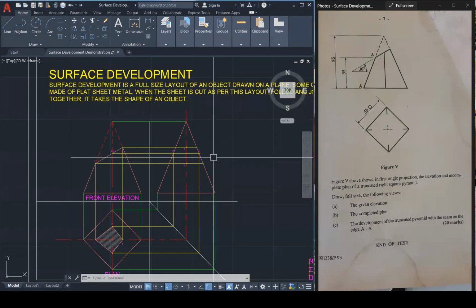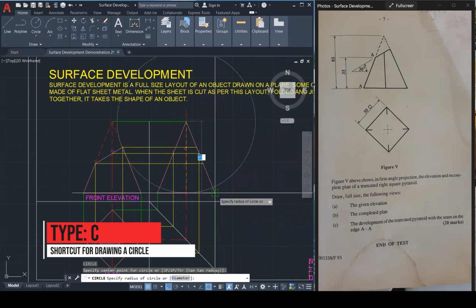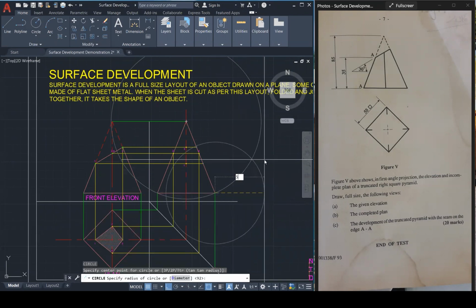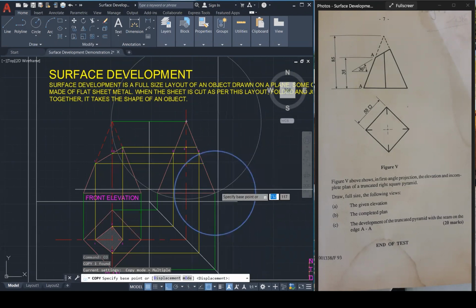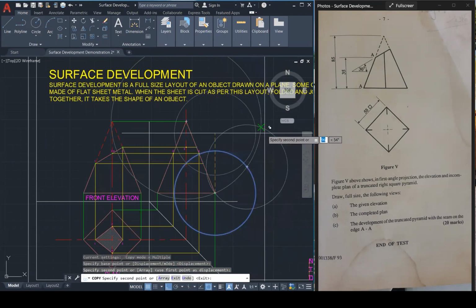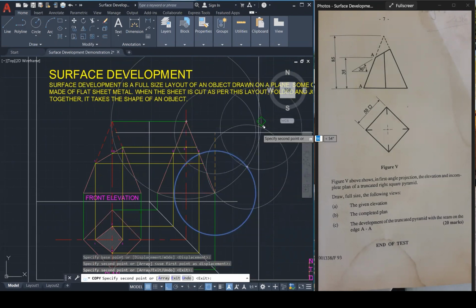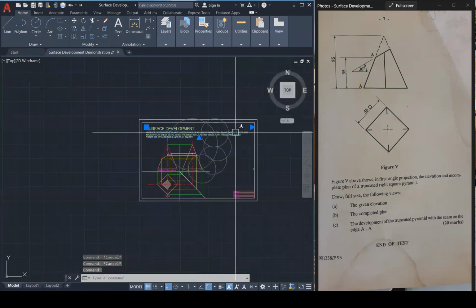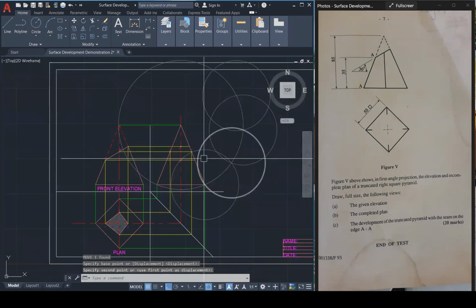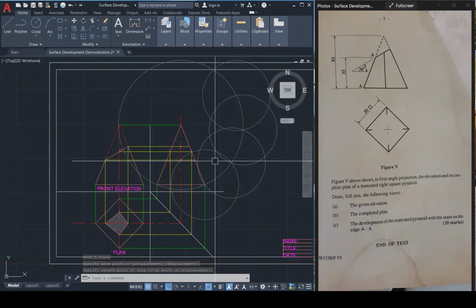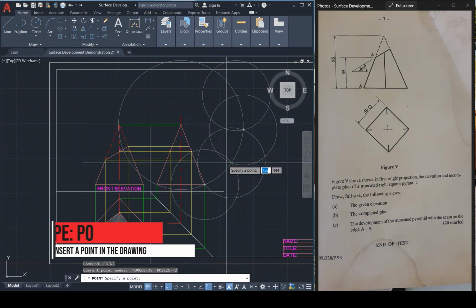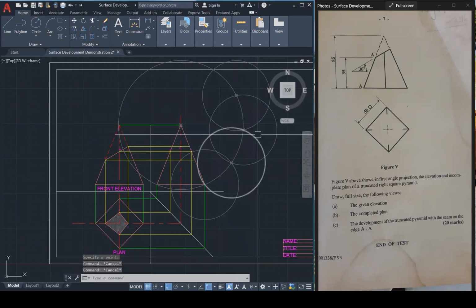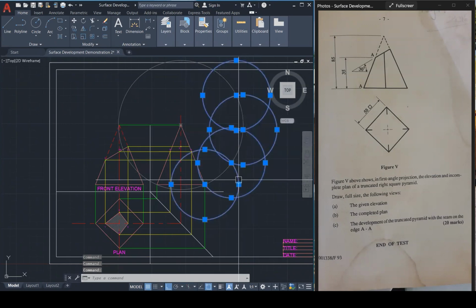Let me explain this. You'll probably understand it once you start drawing in AutoCAD. Use circle, open up a circle to this point here. Then circle again, and open up a radius of 50. Walk the circle, move it. That's what I mean by walk it. Keep it locked. So that's 1, 2, 3. I'm going to move the title out of the way because we don't need that now. And now I can trim this. Very confusing, so I'm going to put points. A point goes there, there, there, and there. Now remove these circles; these are just construction circles.